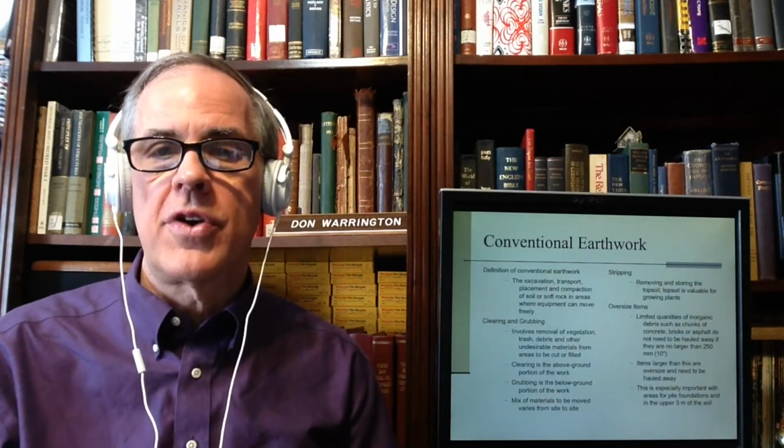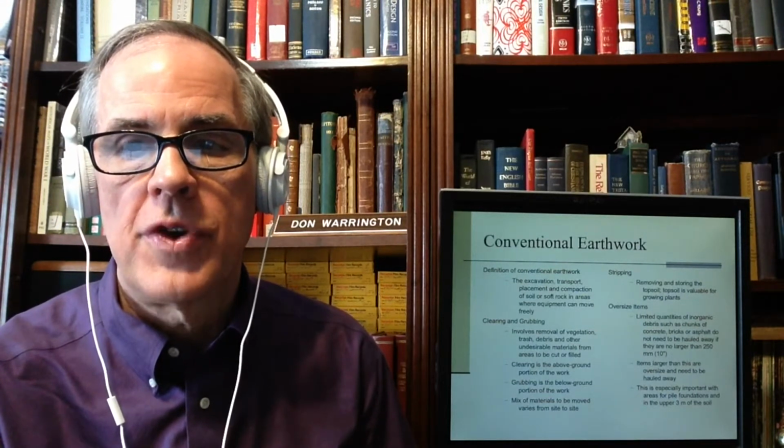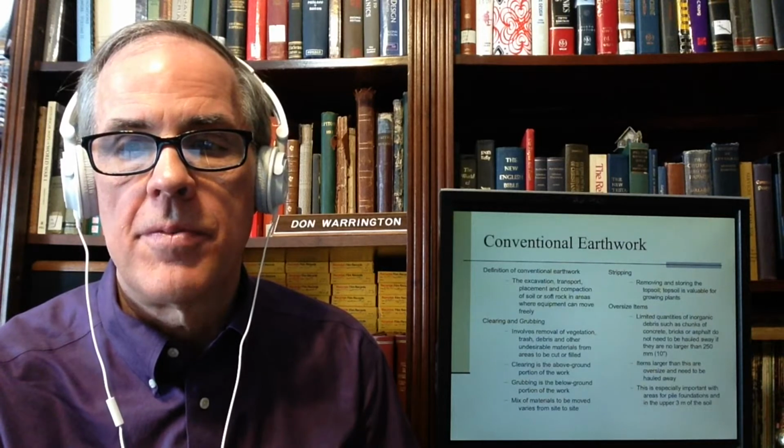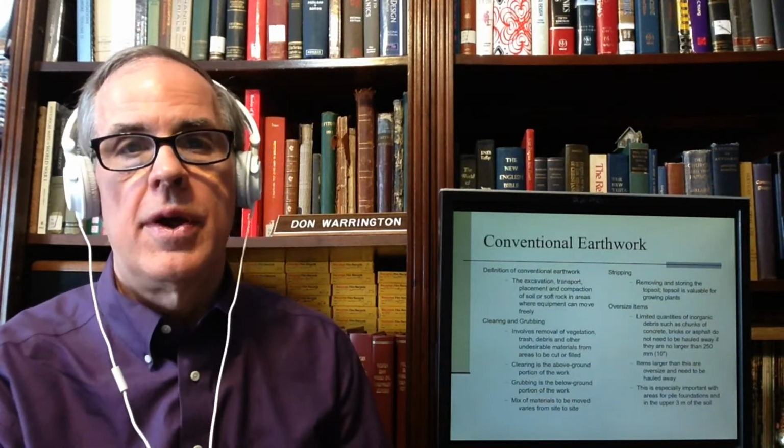Conventional earthwork starts with clearing and grubbing. Usually you don't want to try to do a lot of earthwork when you've got a lot of overbrush. And then you strip the topsoil and either remove and store it, or you can also sell it to somebody else. Unfortunately, that's the way a lot of development is done, where they actually sell the topsoil, and then you try to grow something and the house is built on it, and you're going to have to put sod back on it.